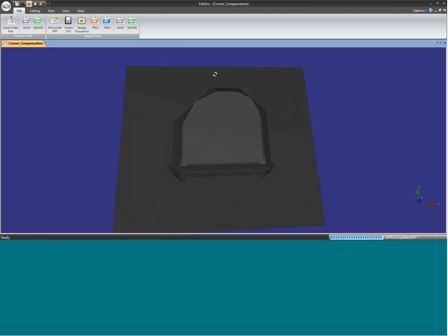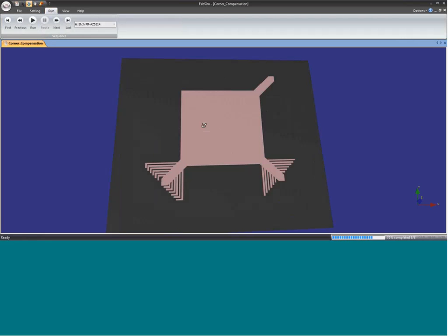And what that means is that in this case we're doing a wet etch of silicon, and you'll see that it actually has the correct behavior that you would see in silicon wet etching. So if we go back and look at this mask layer that we defined on the silicon wafer, you'll see that it has these corner compensation features.